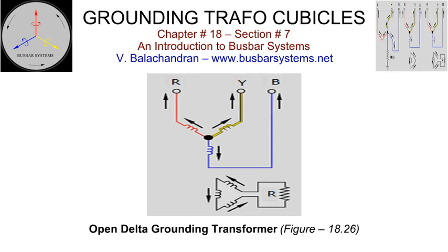Single-phase transformers with shell-type construction can be installed in individual compartments of the surge protection voltage transformer cubicle when separately installed. The line terminal of the primary winding is connected to the tap-off bus and the neutral terminal is connected to the earth in each of the cubicle. The low-voltage windings are externally connected to form an open delta connection to provide path for the zero-sequence current to flow through the resistor.